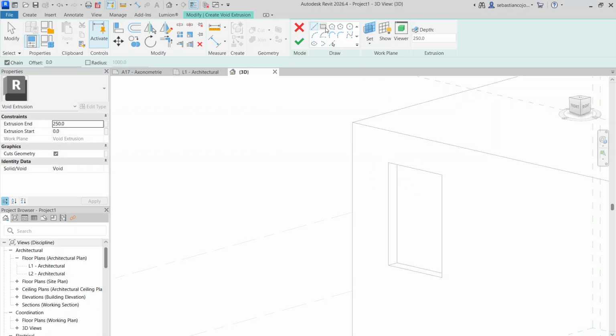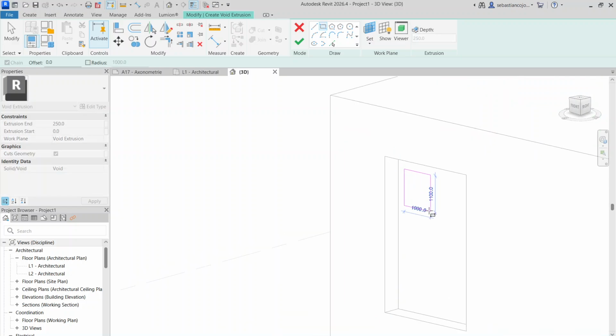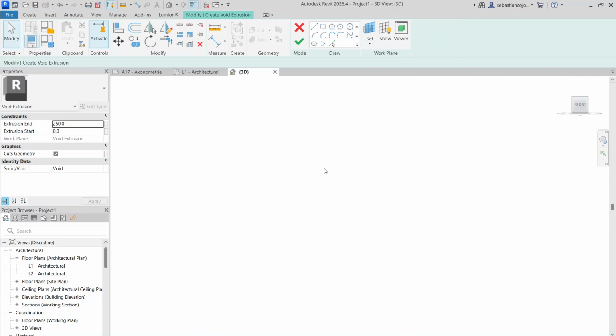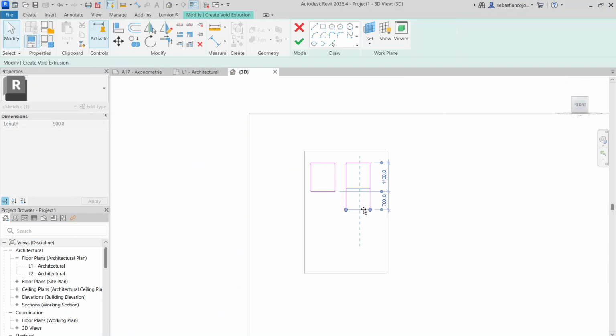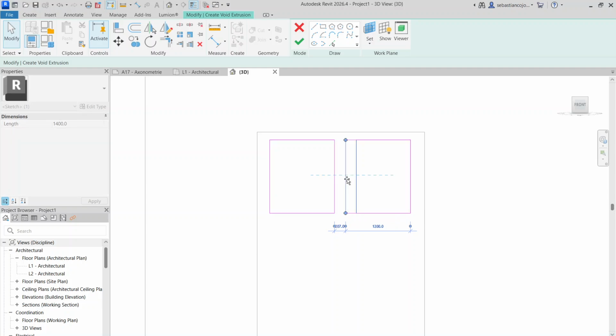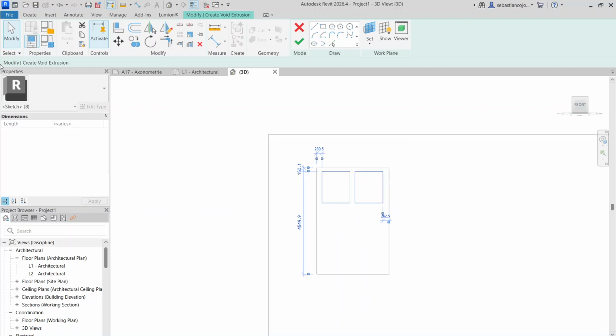And make sure that you select the right, let's say, the right plane. I'll go to the front once again and try to configure. Make sure that you have the right plane selected, because if you don't, it will be a problem and you won't be able to intersect those volumes. As I told you, there were those two